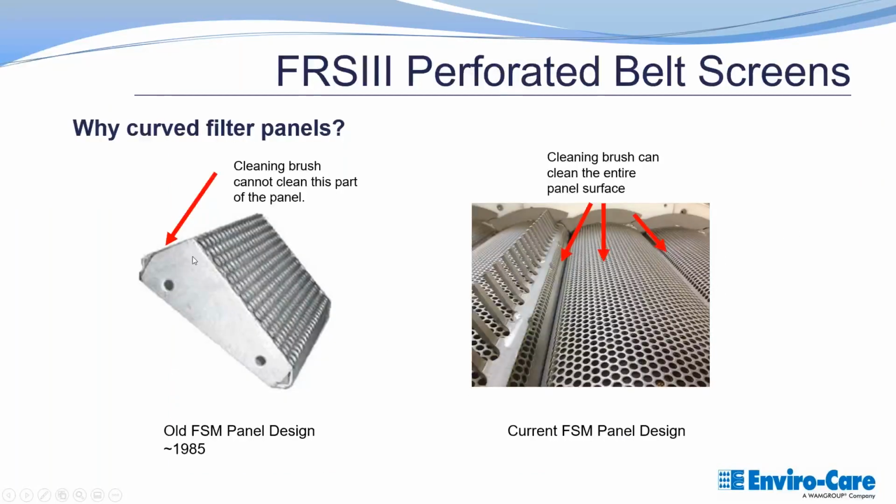These panel designs have evolved over the years. The initial panel design introduced by FSM when they introduced the technology had a ledge to it. The idea being, sticks and stones and other debris that doesn't literally stick to the perf panels will then sit on those ledges and be brought up and removed that way. What they found was, A, it's not very effective at removing that because you have to wait until the panel comes all the way around to actually have it rest on the ledge to bring it up.